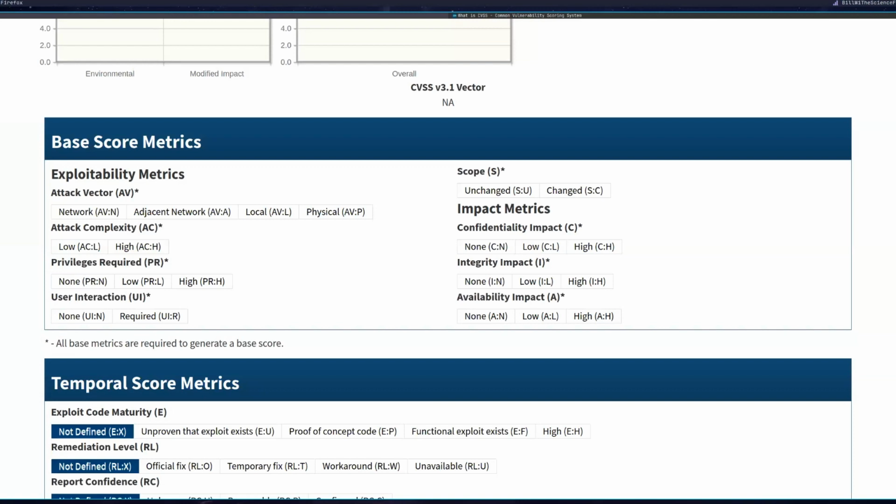Most hardware vulnerabilities that you're going to do when inserting actual vulnerabilities into Verilog are going to be local or physical. So for this, we need to be able to insert a key. It's just a raw AES core. We're going to call that a physical vulnerability. Attack complexity, it's a very low complexity attack. You just need to know the one key that is the backdoor to everything.